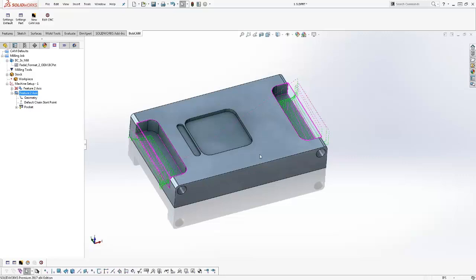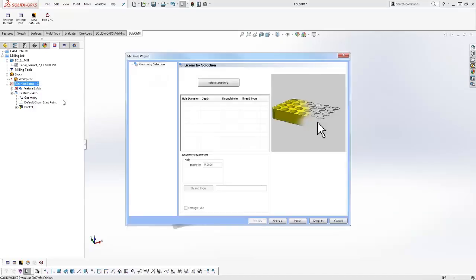Now, you bring up a really good point, John. You talk about drilling slightly oversized when you're doing tapping. You may have missed the first part of this webinar, which is when you're tapping, if I do a tap cycle, the tap is actually based off this thread type. It's not based off of a SolidWorks hole library. It would read the hole size, but it will actually override that for your pre-drill hole based off of the tap that you select from the thread library.